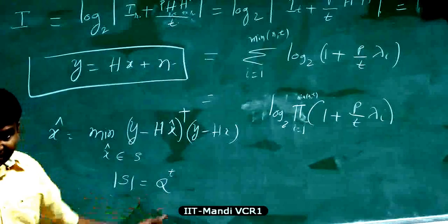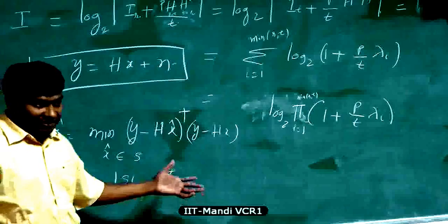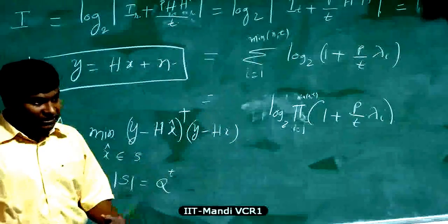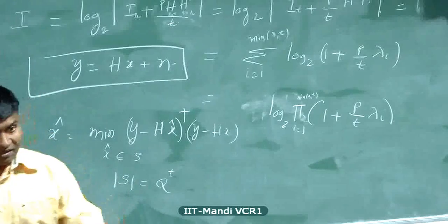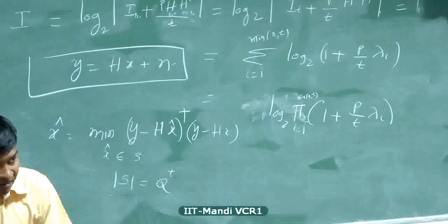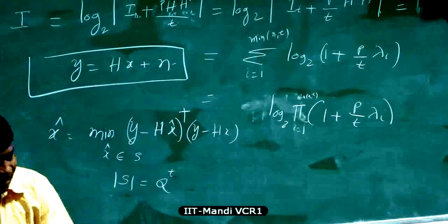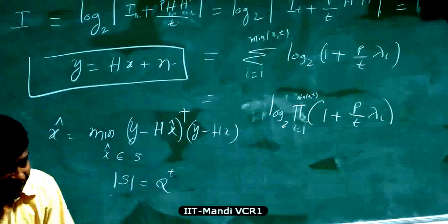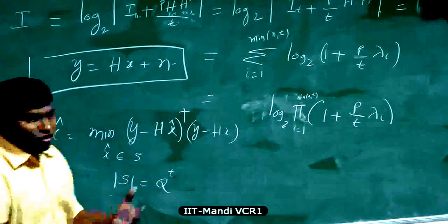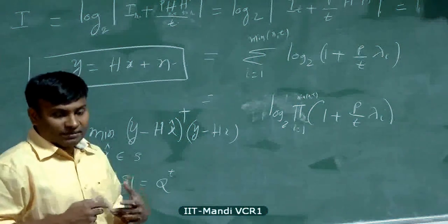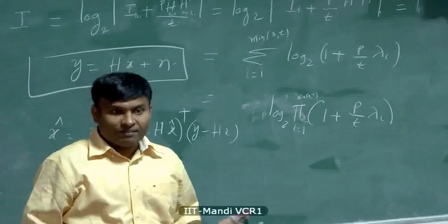Well, it's a nonlinear receiver. It can perfectly, you can have 2 transmit and 1 receive, and you can still resolve 2 streams. Well, there is an SNR penalty you have to pay because you are sending more streams than the receiver can support, but you can nevertheless separate them. Well, you can think of them as jointly encoding those 2 streams in space using a matrix.